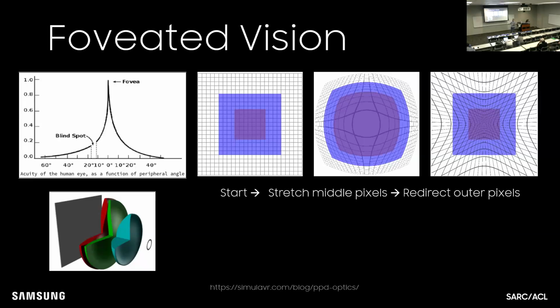Another thing you can do is this warping, which is really interesting, and which is what most of the VR goggles do. They use something called the pancake lens, where they take your normal grid of pixels and highlight the importance, growing the center and making the outside smaller. Then they de-warp it, and it looks clean, but what you're actually doing is shoving a lot more detail and a lot more of those pixels in the center. On the output of your display controller, you're mapping something that looks like this, and then when it goes through the pancake lens, it comes back normal.